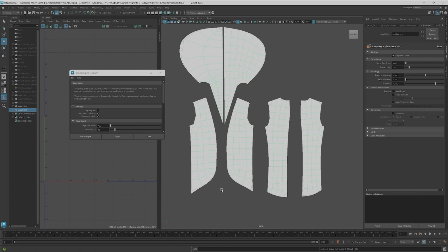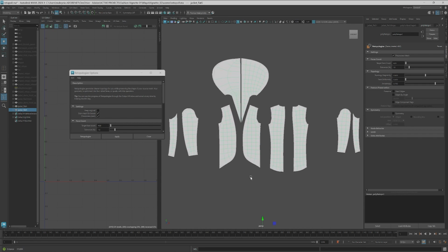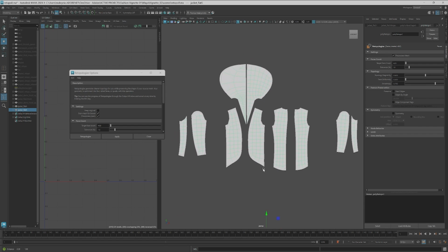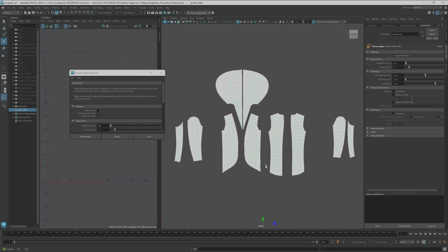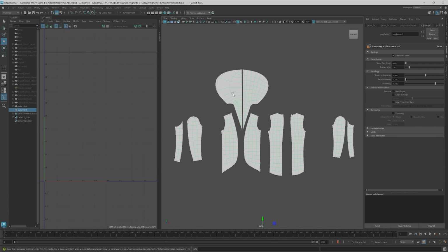Sometimes the new pieces don't align perfectly with the old ones, so there are differences on the external edges and corners. To correct this, we can snap them back onto the original pieces to ensure that their edges align perfectly. The internal topology of these pieces can vary, even if it is always regular quads, as long as their edges correspond exactly with the original edges. If the topology results are not good, you can always adjust the target face count and try again.